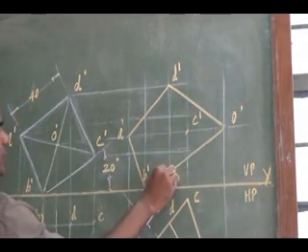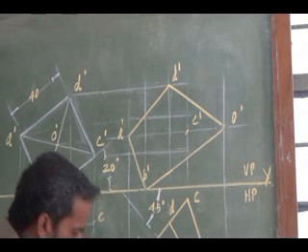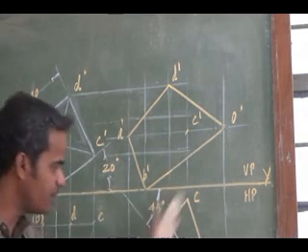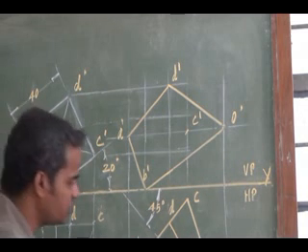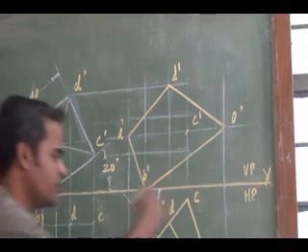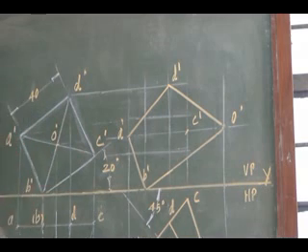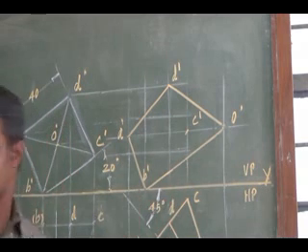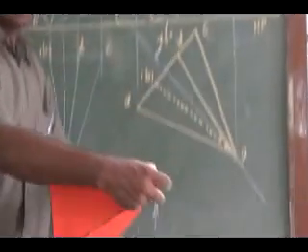Then as per the second note, you look at the top view. While looking from the bottom, is the base fully visible or partially visible? The base is not visible for me. I can see some of the edges and some of the edges are hidden. That is, above the axis is hidden, below the axis is visible. In this orientation, the base is not visible, you see. It is tilted like this.